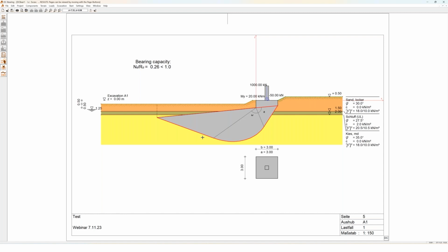And as I said, we have this really small steep slope here, and the coefficient lambda for the ground inclination just works for an endless slope. So the lambda is calculated for the slope which would continue in this direction then. But we have a small slope here which ends here.